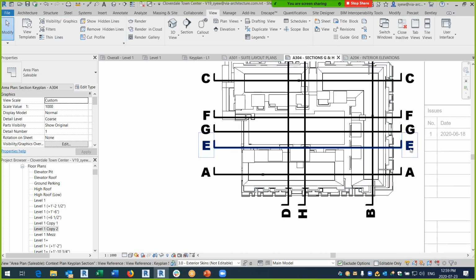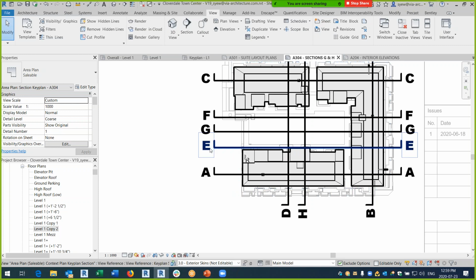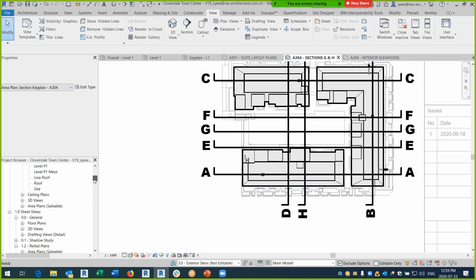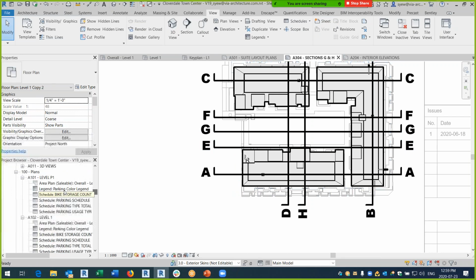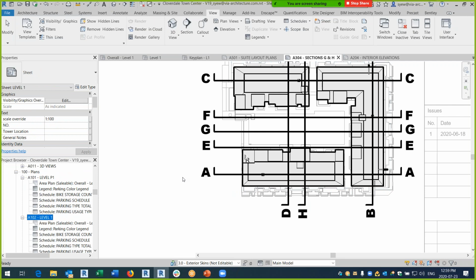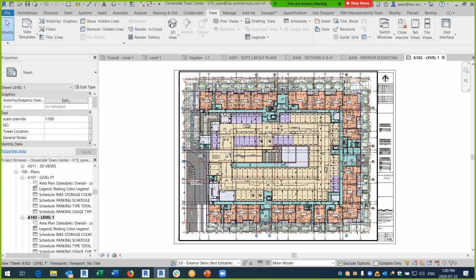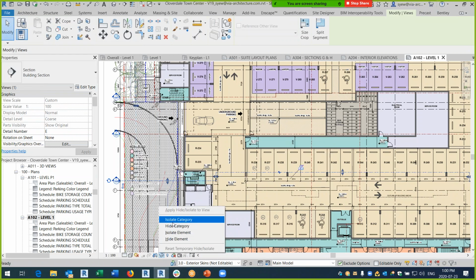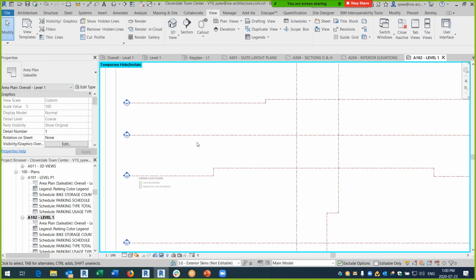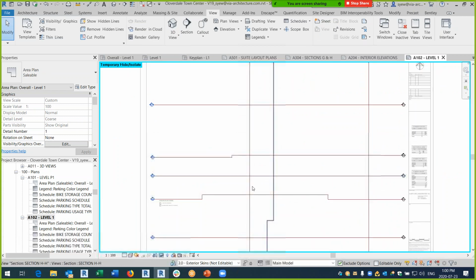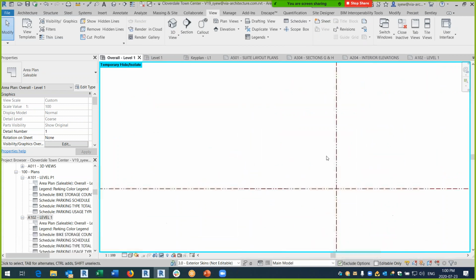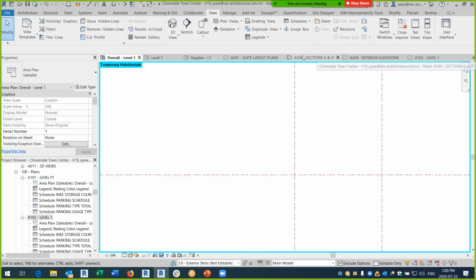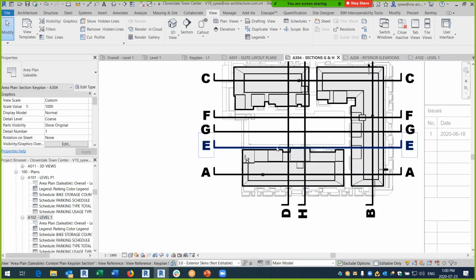When you're doing a section, sometimes this section cuts right into the balcony. And in Revit, I have a jog. If you want to see the plan itself, it has a jog. Sometimes with this particular one here, I'll just activate it. I know the jog can be very problematic. You notice that I have a lot of jogs. If I had to show that in Revit for this section, you notice it's not going to show the jog.